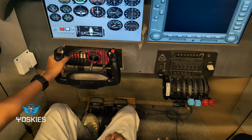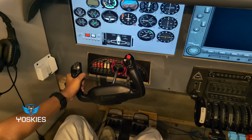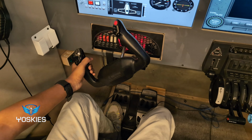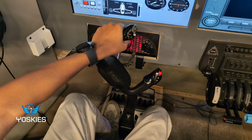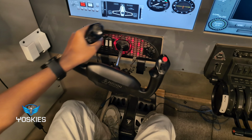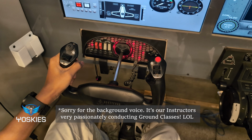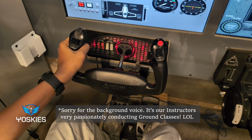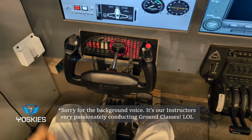Okay, let's talk about the primary controls of the aircraft first. This is your yoke. When you turn it to the left, the aileron goes up on the left and down on the right. When you go right, the aileron goes up on the right and down on the left. Now pitch up, the elevator goes up; pitch down, the elevator goes down. So this is the yoke.